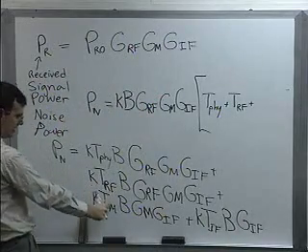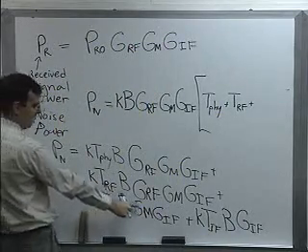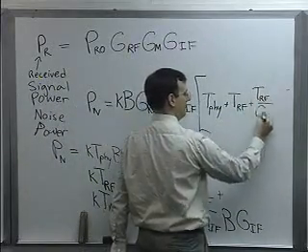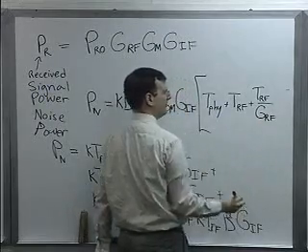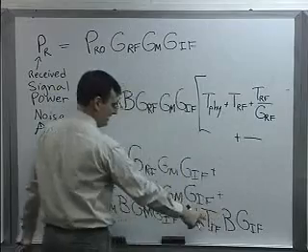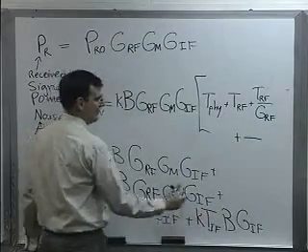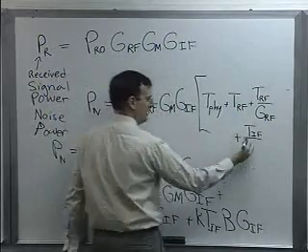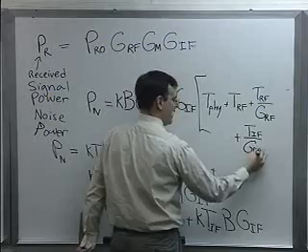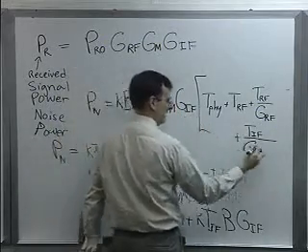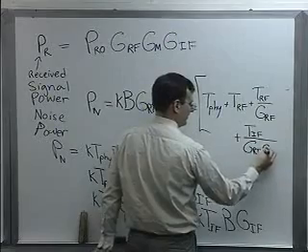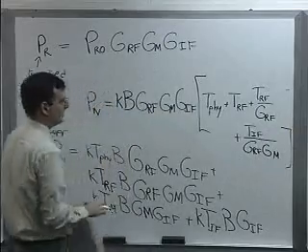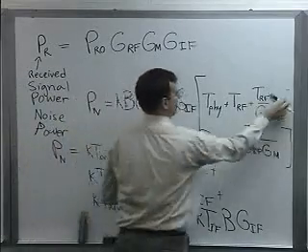Now, the next term, because it's the temperature of the mixer, and because RF doesn't show up there, I've got to take that temperature and I've got to divide it by G_RF. Likewise, down at this IF amplifier, I don't have G_RF or G sub M, so I just got to divide it by both of these if I want the math to work out, my factorization of these three gains. So, this must be T_M. Shouldn't it be T_M, yes, thank you.